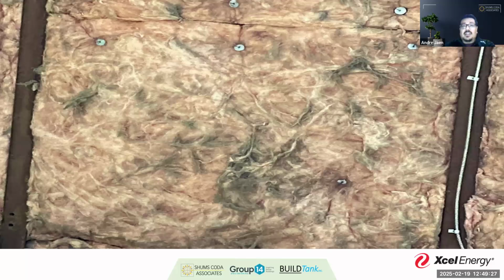So I've shown this picture a lot. A lot of people think this is mold or mildew. What this is, is dust. This is dust particles that have just kind of fed into this insulation. And you can see where it's gotten more spindly in those places, and it's certainly not as pink and fluffy as it once was when it was put in. And that means it's not doing its job very well. And if that air can carry dirt and dust, it certainly can carry moisture and mildew as well. So those things can certainly get in there. But this is what we're fighting at a very basic level, right? We're preventing this from happening and trying to keep these materials as durable as they can be for the lifetime of their installation.